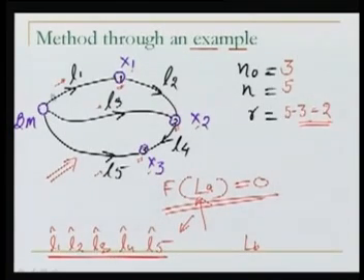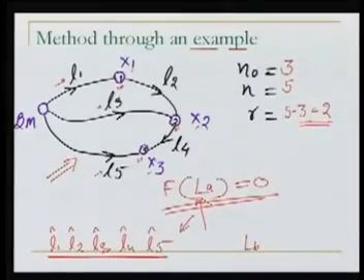So we are finding the difference between the benchmark and point number 1, L1, between point number 1 and point number 2, L2, and between point number 2 and the benchmark. If I add those differences in elevation, their sum should be 0, because we start from a point and reach the same point again.